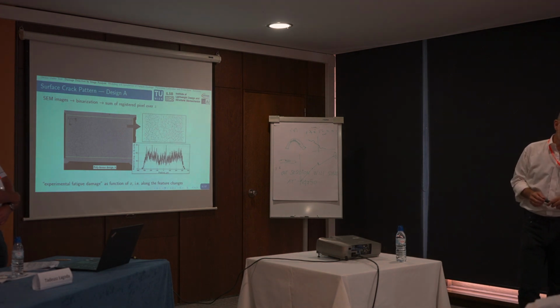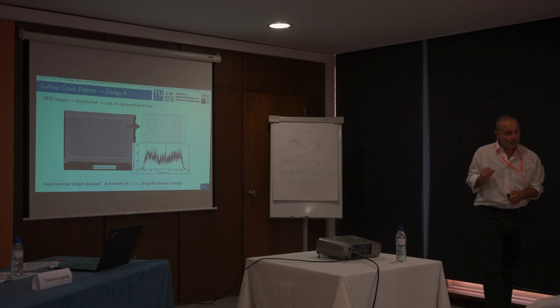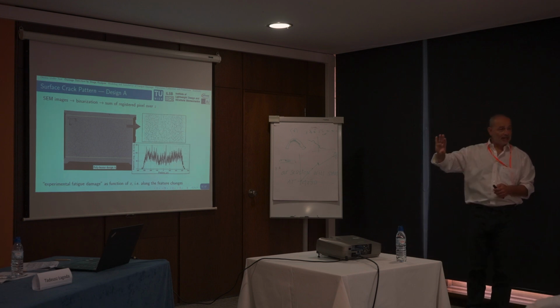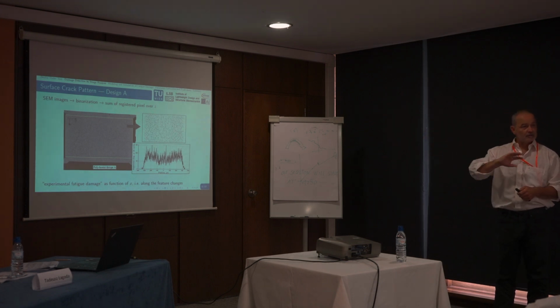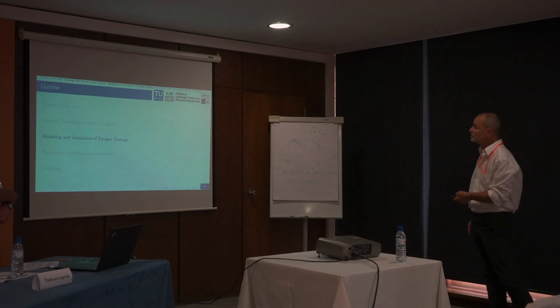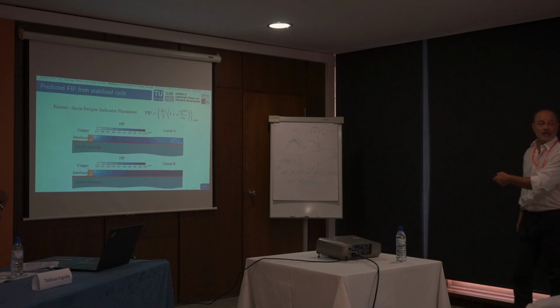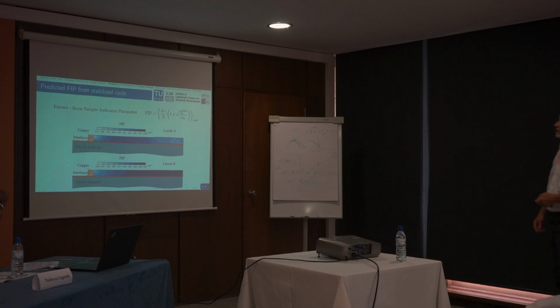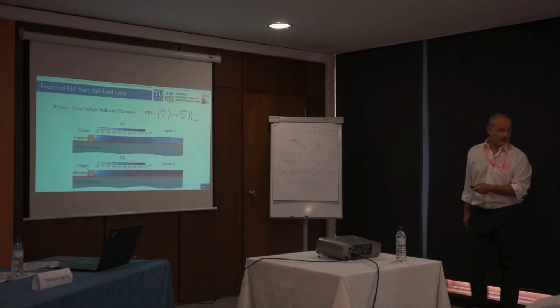Okay, so first you run the thermomechanical analysis and get the stress and strain output to drive the fatigue model. We run it sequentially coupled. We do the thermal analysis before, and then we do later the elastoplastic simulation. And the elastoplastic simulation gives basically this. What does gamma mean? Gamma is the shear strain. So that's the Fatemi-Socie fatigue indicator.